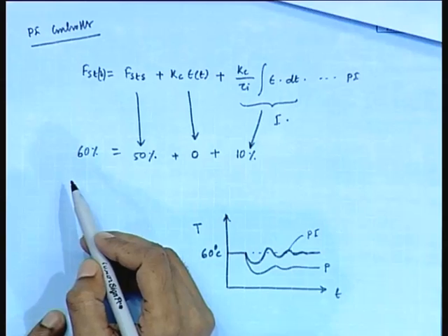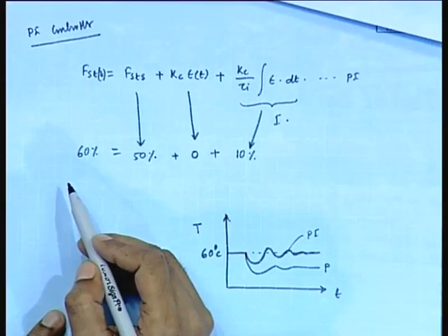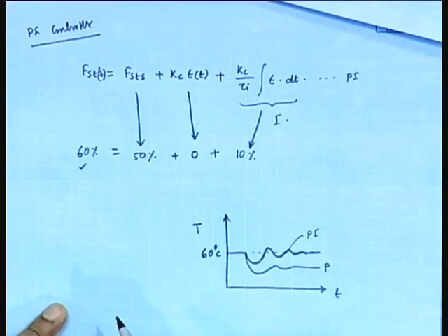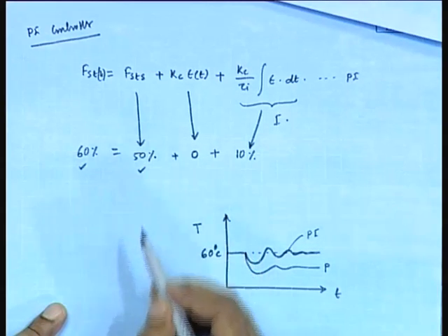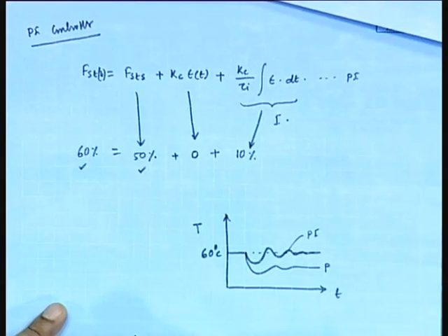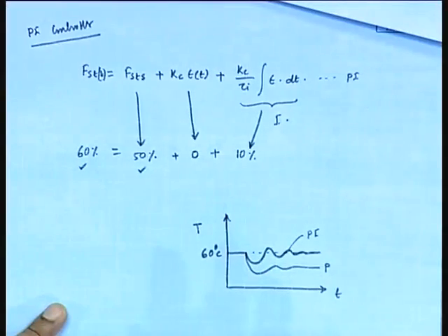Now, you see, if we introduce a step change in Ti from 25 to 20 degrees Celsius, then there is a need to open the steam valve 60% open. There is a need to maintain 60% opening of steam valve. So, this is 60%, steady state value is 50%. If PI controller eliminates the offset, then definitely error should be 0, that means this is 0.